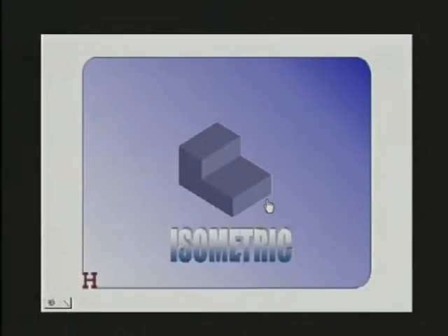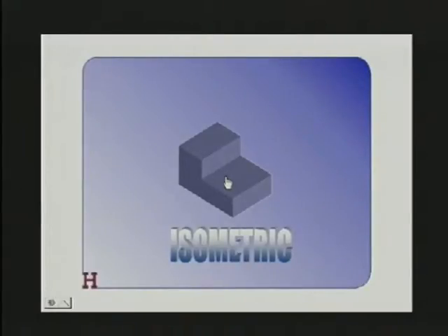The nice thing about isometric projection is that it's close enough to what we see with our human eyes that someone who is not trained in engineering drawing can recognize what they're looking at. It doesn't take a lot of training because, although it's not exactly what we see with our human eyes, it's not exactly perspective, it is close enough so that average people can understand this. However, it's inadequate for completely showing dimension.